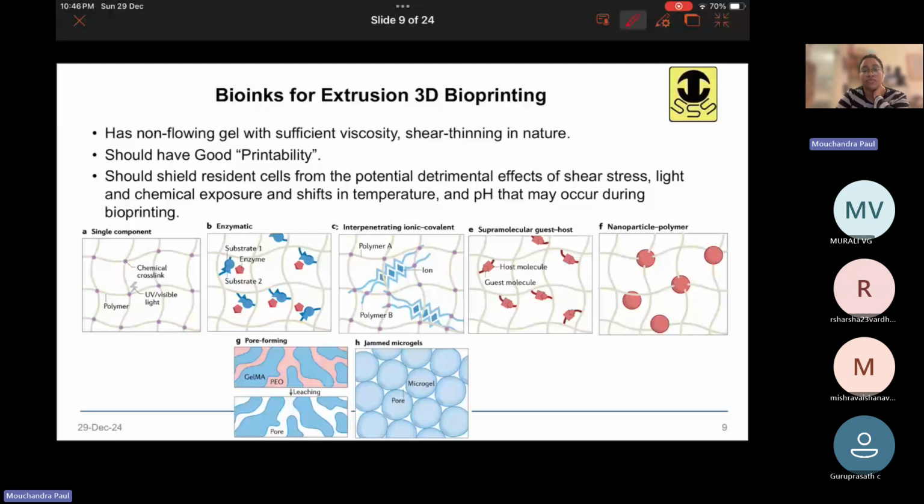As soon as we remove the shear force, the viscosity increases. So with increase in shear, it becomes thinner, the viscosity becomes low, and it flows easily. But when the shear is removed, viscosity becomes high, so the flowable capacity reduces.